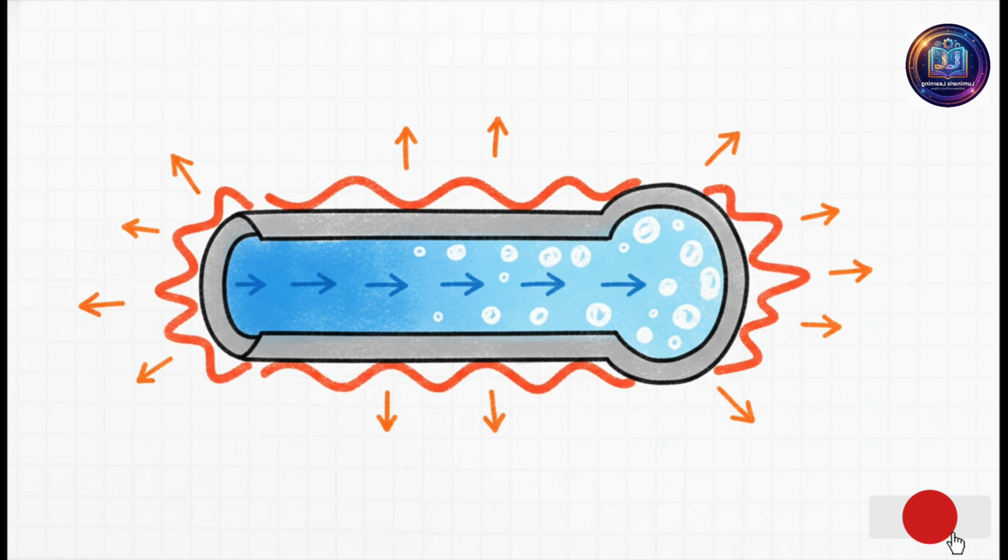So let's just cut through all that noise. If you're going to remember just one thing from that super long definition, make it this. It's a water tube boiler. That's it. All it means is the water is inside a bunch of tubes, and the crazy hot furnace gases flow around the outside of them to heat it up. That single design choice, it's the key to absolutely everything that makes this thing tick.